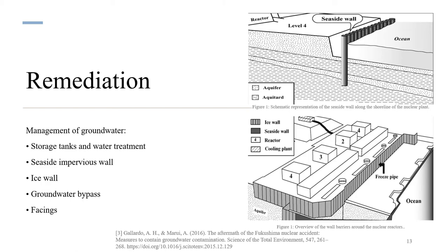Contamination and decommissioning of the Fukushima facility rely on three basic policies: to remove and treat existing contamination, to isolate fresh waters from the contamination source, and to prevent leakage of contaminated water. The problem of groundwater contamination at Fukushima starts in the Abukuma Mountains. It is estimated that 400 cubic meters per day of fresh groundwater flows from the peaks overlooking the complex towards the reactor halls, where it mixes with the contaminated waters generated from cooling operations.